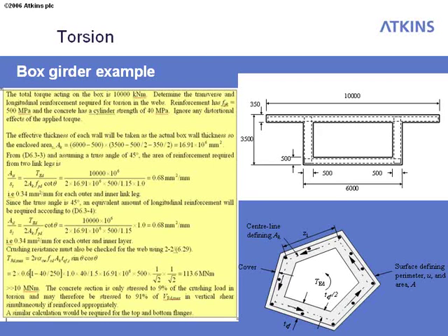As I said earlier, if we want to minimize the vertical reinforcement, we'd go for a flat angle, but that will result in more longitudinal reinforcement, and it's also less efficient for the maximum shear stress. Going for a steeper angle is the most efficient for the maximum shear stress requirement.